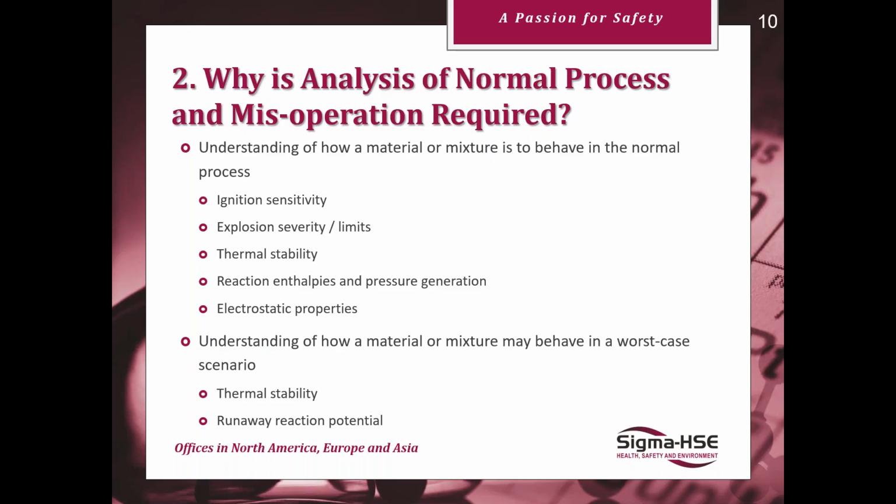Reactive systems, runaway reaction potential, but this is really additive to the first points that are studied. Again, in a worst case scenario, understanding your ignition sensitivity, explosion severity, explosivity limits, these really feed into understanding what may occur in a worst case scenario as well.